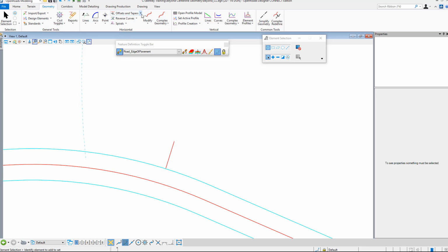Let's go ahead and put my edge of pavements in there, 12 feet wide, 6 feet on either side. Let's do that. We're going to do the entire length of that. Let's say click here, 6 feet. Mirror yes. There we go, that was quick. And I can do a line between points to connect those in the back. Line. Now that's a straight line between them.